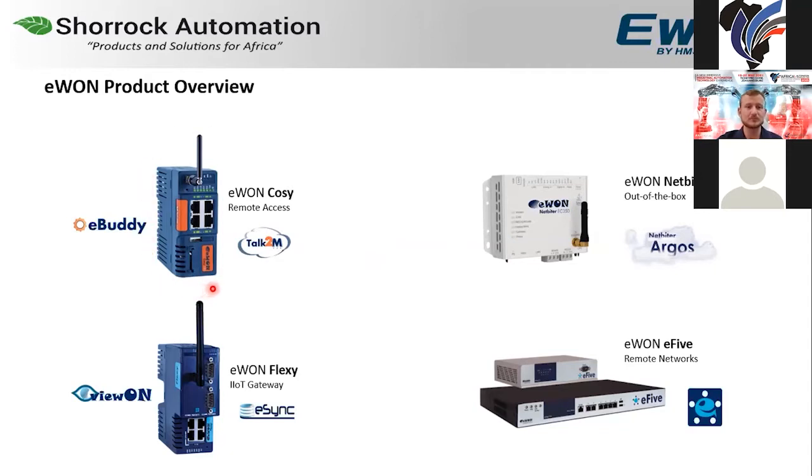Up top to the left, I'll start off with a product called the E1 Cozy. This device offers secure remote access, so that could be remote access to a PLC or an HMI or a PC, any machine that you can imagine. Then moving up top over to the right, we have what we call the E1 Net Biter. The E1 Net Biter also promotes remote access, but is more focused on gensets or asset management, where this device comes with GPS functionality, and it also has a J1939 or CAN interface, for typical applications such as genset monitoring or mining vehicles, etc.